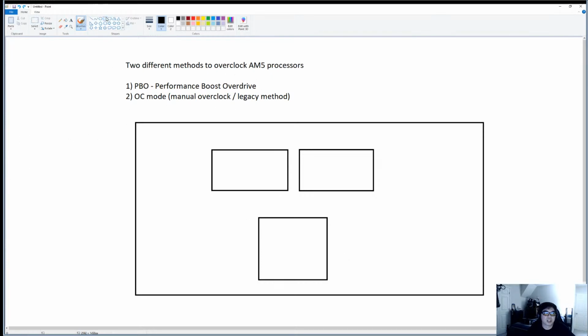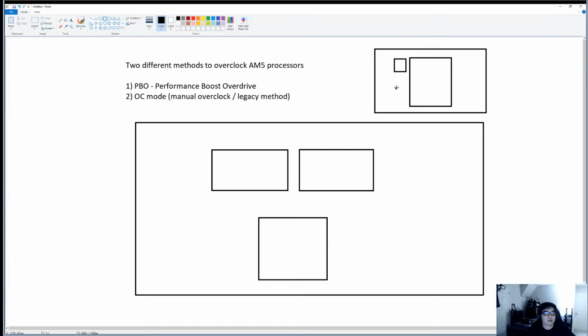If you think of the die up here, I'm just going to draw it out. It had the GPU die in the middle, and around it they had 4 blocks of HBM memory, each 1 gigabyte, so essentially you had 4 gigabytes. What's interesting about this design was the interposer, which is kind of like a substrate fabric that links the memory to the GPU die.